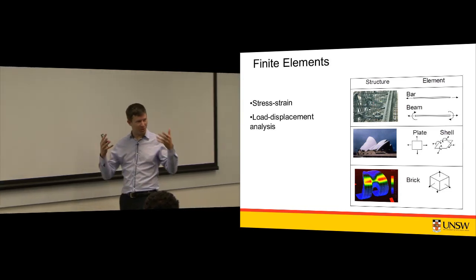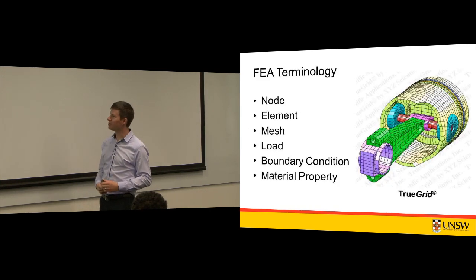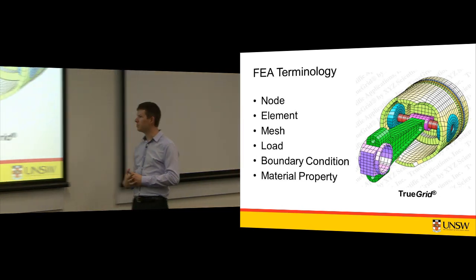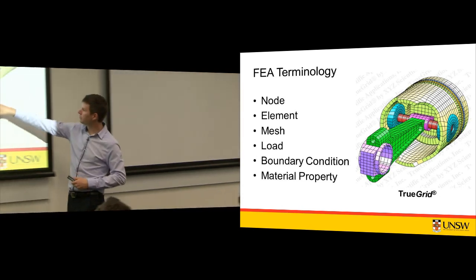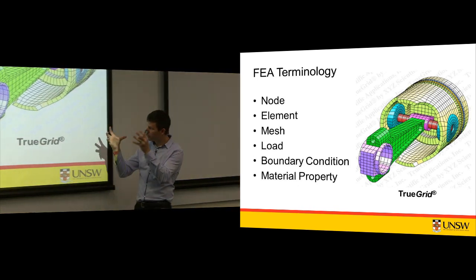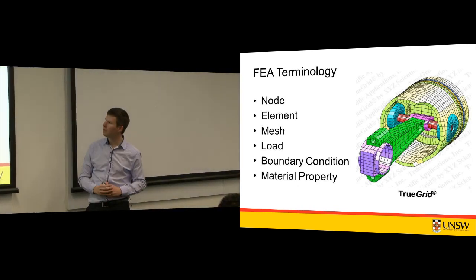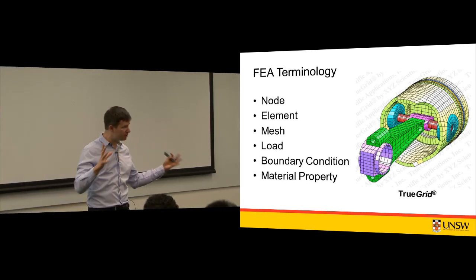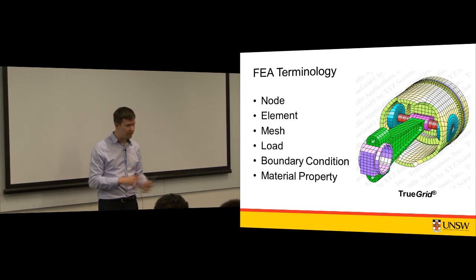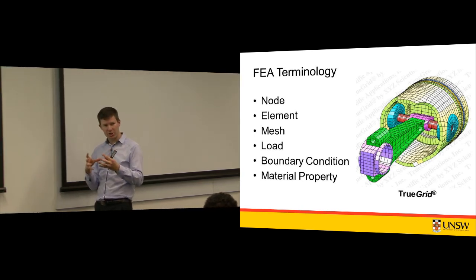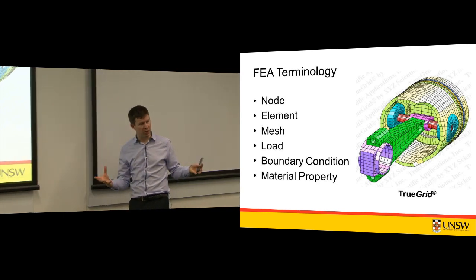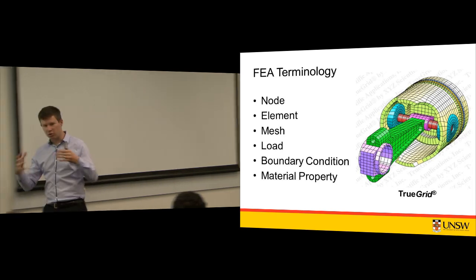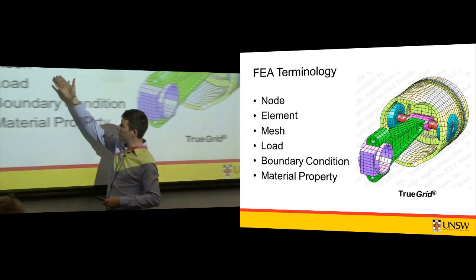You know, engineers more so than other populations you would get with that analogy. So it's a brick, even if it doesn't look like a brick, if it's not a rectangular prism. So elements, so the volumes of material between the nodes. Mesh is the word that we use just to describe the breaking up of a continuum body into discrete chunks. And you could have a fine mesh being small. You could have a coarse mesh or large mesh being large elements. So large elements, small elements. You start to talk about that. You talk about your meshing or your mesh.